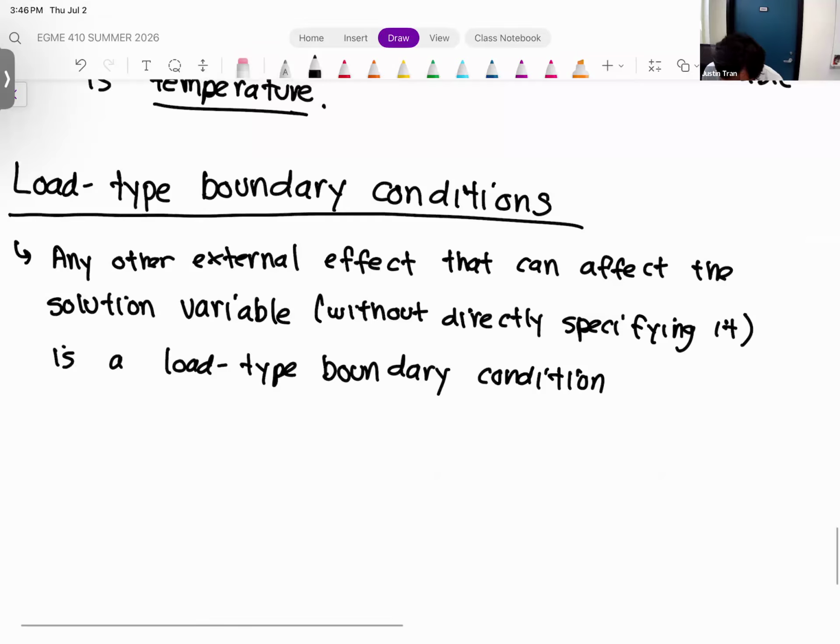Okay. All right. So some common examples that we will see in ANSYS. And so, we've already used one in our previous activity, like a pressure. Pressure is essentially just a distributed force, right? So we know that when we apply a force to a structure, it's going to cause it to deform, but it's not causing it to deform directly, right? So we're not saying that the pressure is going to force a deformation to be X, right? We're just applying the pressure, and we're going to see how the structure deforms as a result.